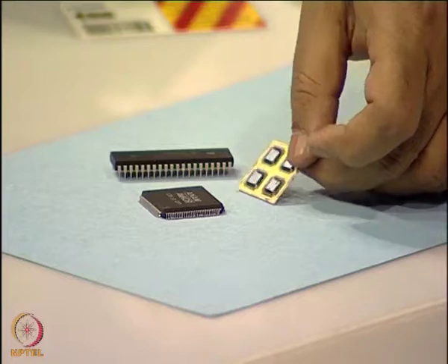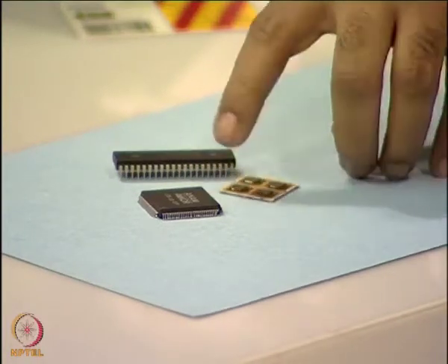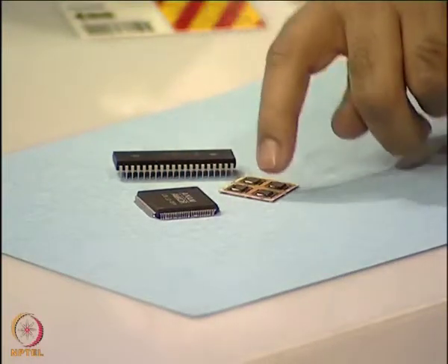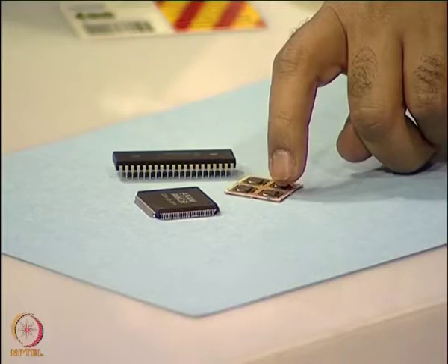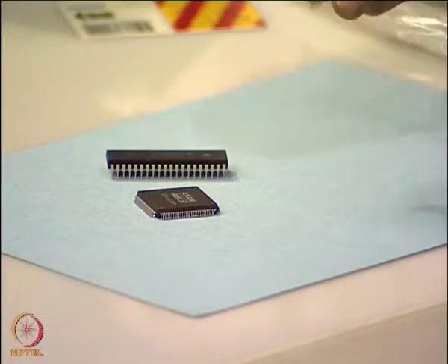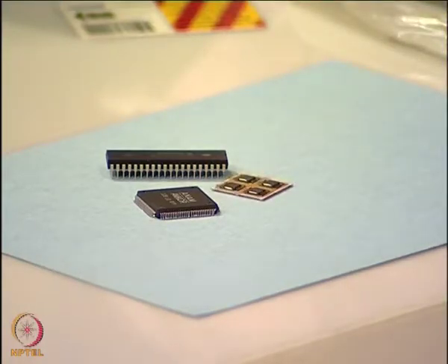unpackaged die, bare die you can see, and these are interconnected on a common substrate, and this can be packaged like this device. It can be packaged with the encapsulant here, and this will have its own set of IOs, and this will be a multi chip module. In this case, there are 4 die or dies that are interconnected on a common substrate.